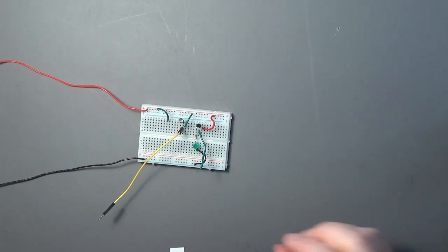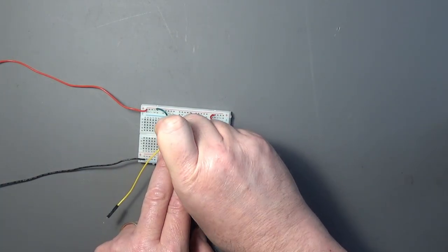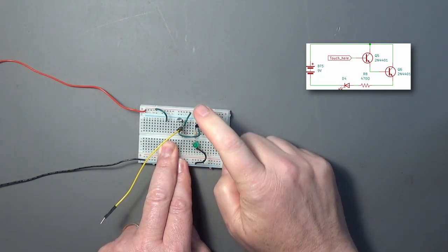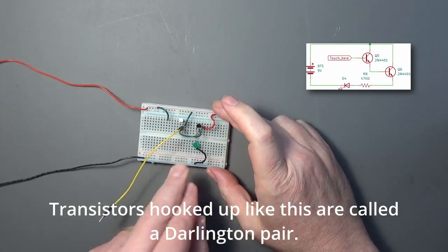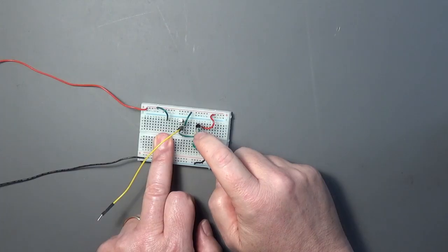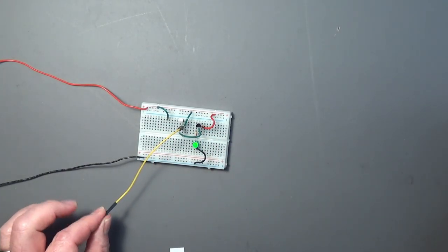Okay. So what I'm going to do is plug this into the other transistor here. So now the base of this transistor goes to the emitter of this transistor. Now for this transistor, the collector goes to plus, the base goes to this guy, and the emitter connects to the base here. Now if I touch this, the light comes on.